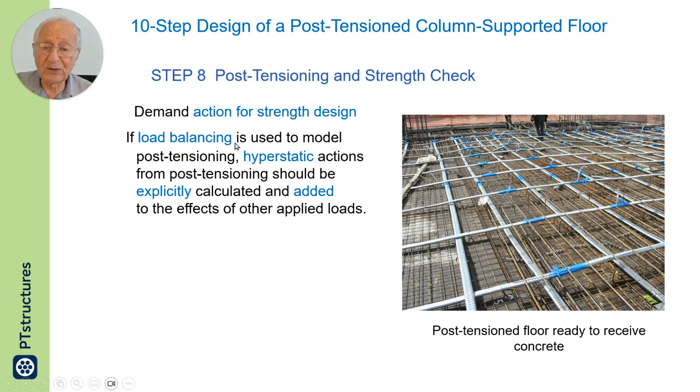If balance loading is used, which most engineers use, that is the common practice in the US, we have to calculate the hyperstatic actions from post-tensioning and include them in our load combination. This is required if we use balanced load method of design.